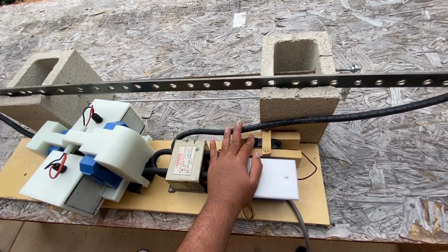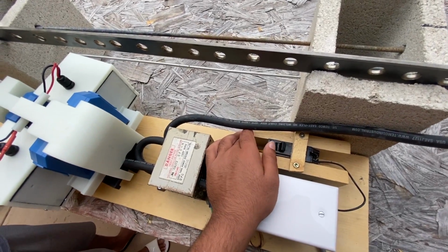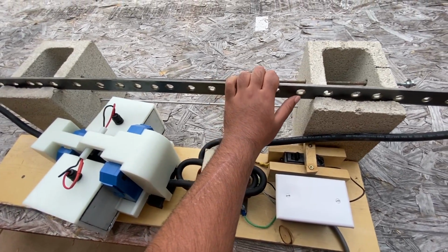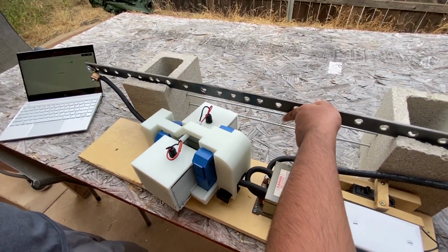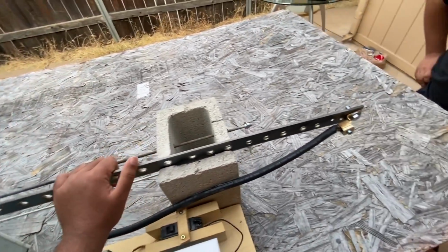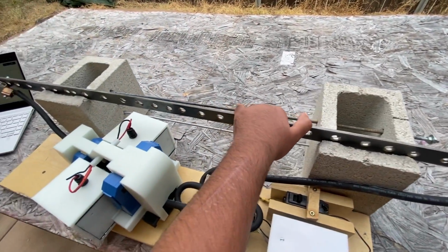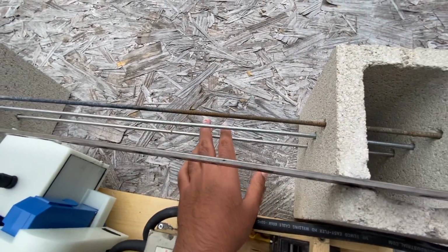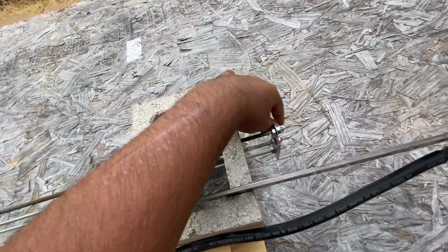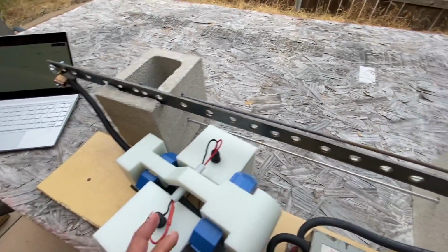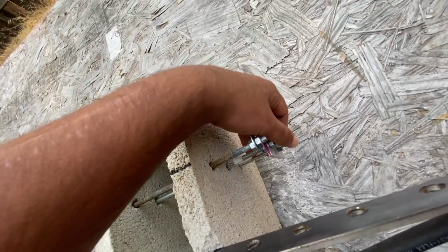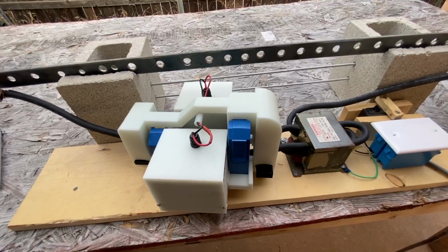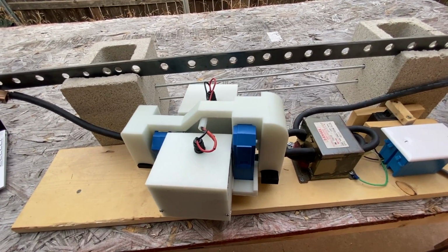We have added a couple safety features, including this breaker, which should trip in case of bad short circuits. This is our 400 amp load bank, just a steel bar. It's pretty nice because it can hold the heat and sustain 400 amps. This is our more variable load bank. It's 3 rods in series, but you can adjust them by moving these terminals, and it produces anywhere between 0 and around 200 amps.